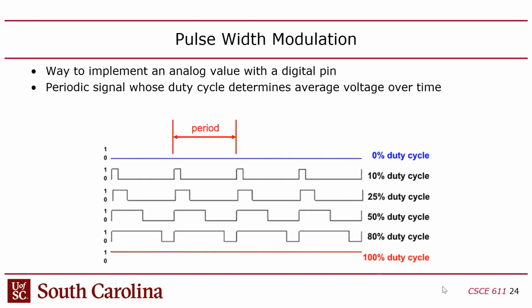Okay, then we talked about pulse width modulation. Of course, you guys use this quite a bit in lab. I think we use this in labs 2, 3, and 4. And this is just setting the duty cycle. Now, by the way, have any of you guys tried using lower frequencies for the PWM? So we've generally tried to target about 10 kilohertz, where we switch this thing at 10 kilohertz, and then set the duty cycle. But is that too fast or too slow?